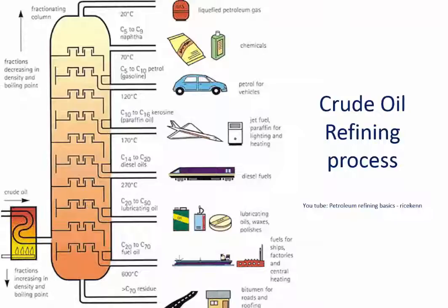Another one is marine diesel oil, MDO, MGO. So we can get different grades of diesel, but high-speed diesels, which is mostly what we're concerned with, use distillate, the same as we use in trucks. And then we can get fractions off for our lube oil, and this is often what we call residual fuel oil or black fuel, which ships and power plants can run on. And at the bottom we get our residues, which is our tar and bitumen.